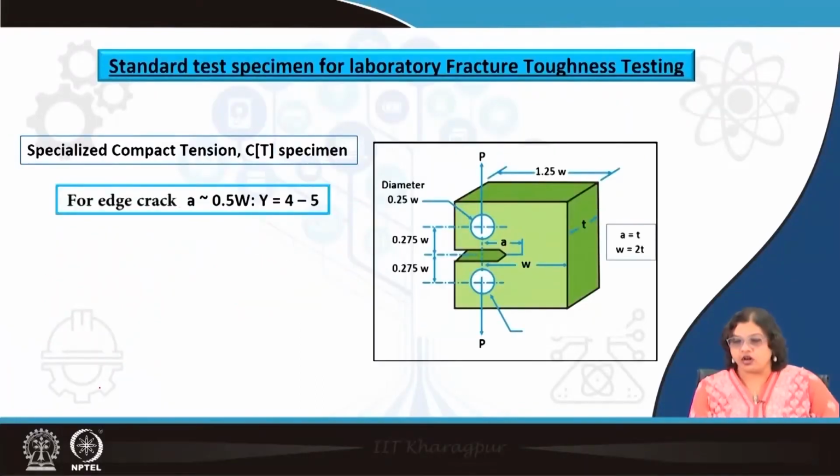Okay. Now, moving on, now that we have seen the importance of Y on the fracture toughness of the material, or the estimation of K actually. Now, fracture toughness of a material under certain condition is a fixed value, right. So, it is a constant value, and if that value of K is achieved, there will be fracture, as simple as that, and this is valid only under certain condition known as the plane strain condition. We will discuss in detail in the next lectures. But for now, we all know that fracture toughness is a certain constant value that needs to be achieved, okay,